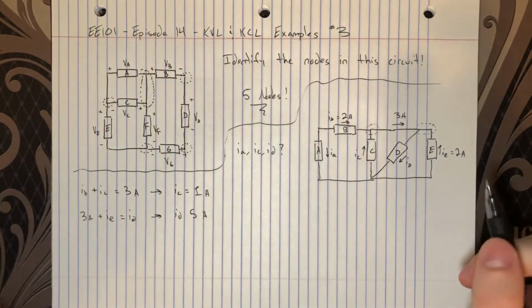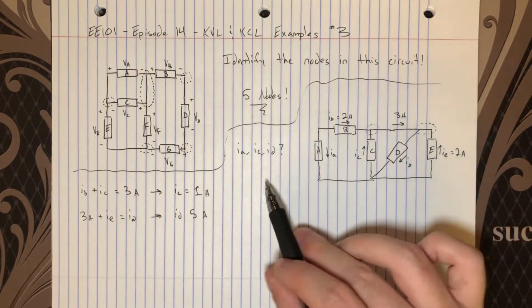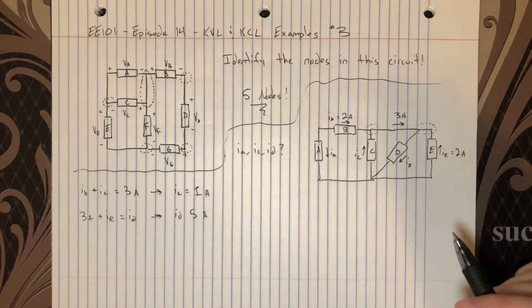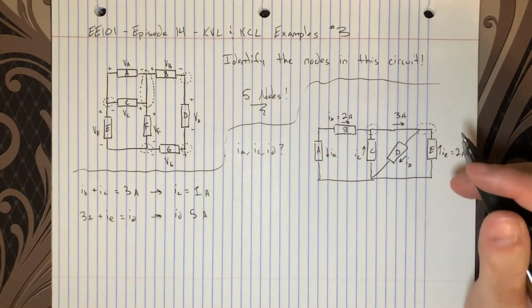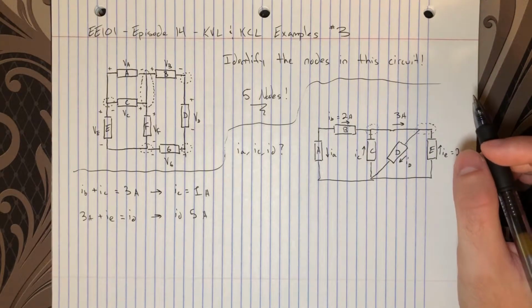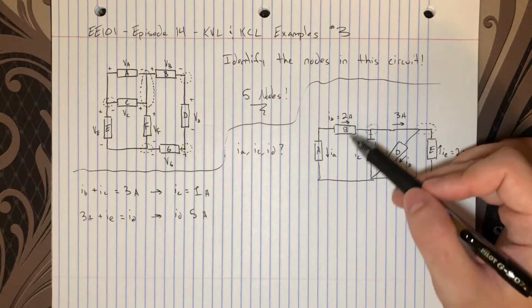Okay, fantastic. Now let's solve for our last piece of unknown here, which is IA. And in this case, I'm not even going to apply a KCL because again, these two elements, A and B, are in series, and all you have to do here is identify the interaction of the current with the reference polarity that we've assigned here.